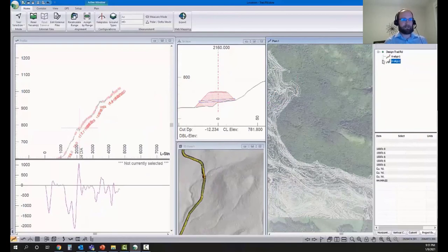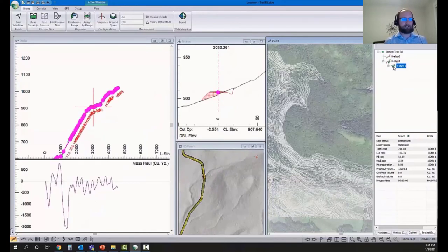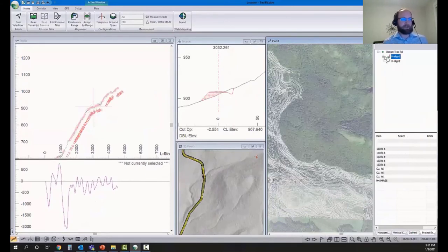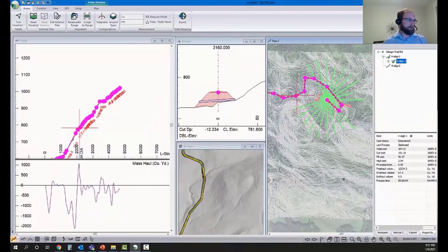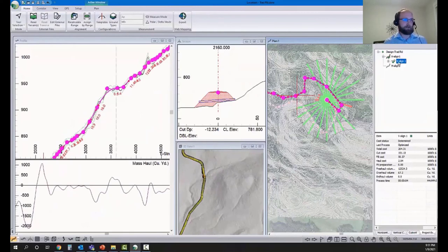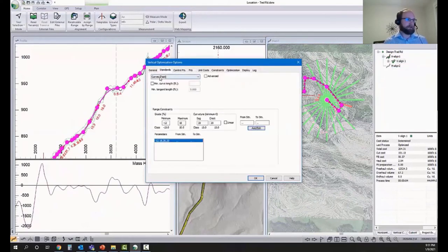So we're down to 211 versus 204, I believe. Now for both of these, I used the fast curves option. So that's curves butted up against each other, no tangents in between them. Probably appropriate for your in-block roads, not great for a main line. So for a main line, I'd go with variable curves and tangents.